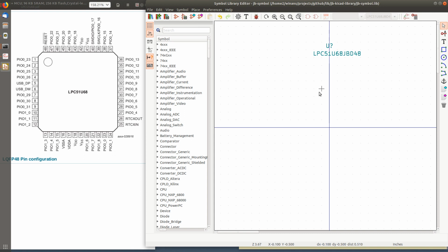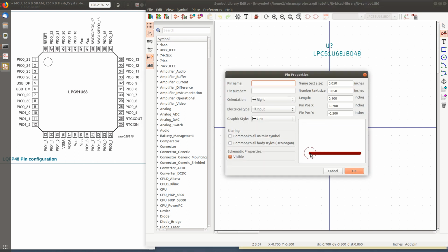Now what are we doing here? We're using basically the same thing as the schematic editor, but instead of putting symbols, we're going to put these pins, or what I like to call terminals, because it's this little round thing and the pin number that are the important and critical things. Most of these we can just use the defaults. I prefer the length to be 2/10 of an inch. We're in inch mode over here, so these are all in inches. This is what the length is of most of the pins on the parts in the KiCad library. I don't know why it showed up as 1/10 by default, but that's fine. You can put whatever you want in there.